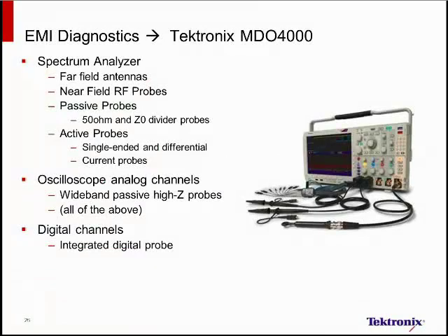An MDO4000 supports regular antennas, biconical, log periodic, whatever we might be able to use. It, of course, supports near-field probes. The really interesting thing on the spectrum analyzer input is that it supports our TekVPI interface, meaning if we have any of our 50 ohm TekVPI probes, we can directly connect them to the spectrum analyzer input. So, for example, we could use a current probe on the spectrum analyzer input.